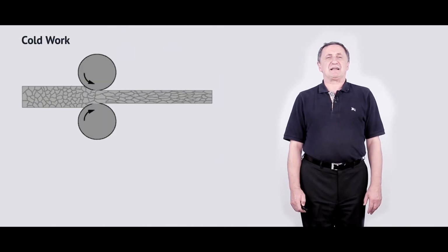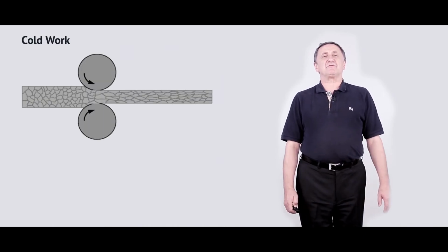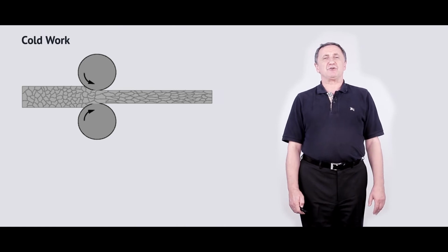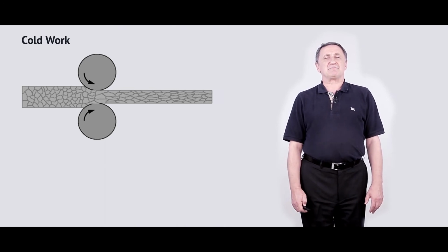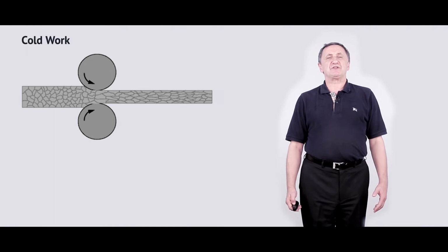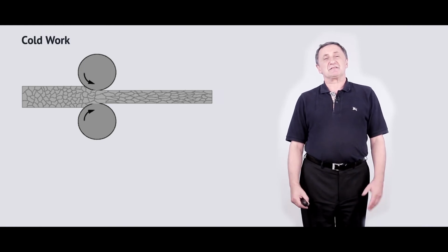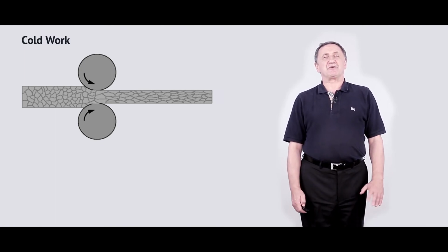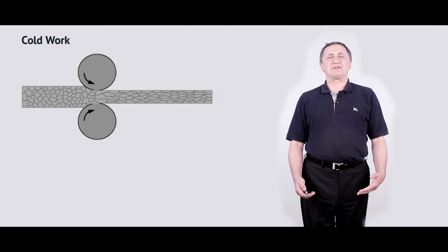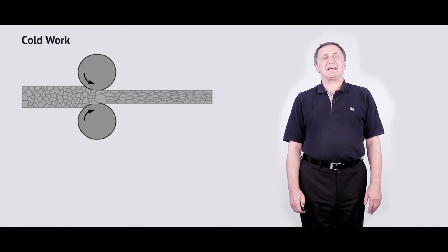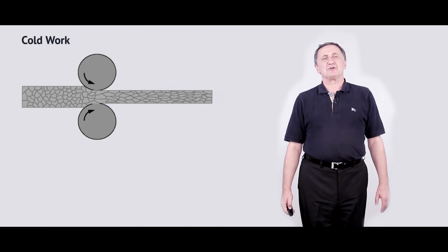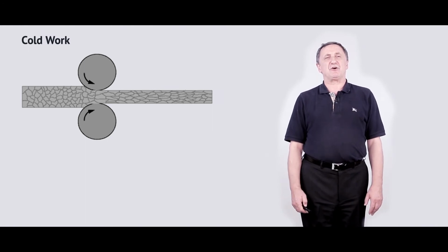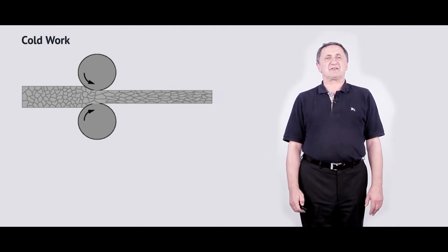How do we reach strain hardening? For example, one approach is cold work, as you know. You have to apply some strain to your material, which leads simultaneously to a decrease of grain size and an increase of dislocation density. Altogether this should lead to a significant increase of yield stress and tensile strength.